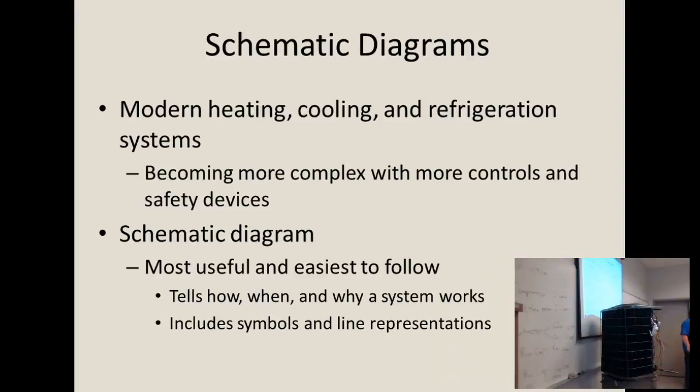What does the T stand for? T stands for load side. L stands for line side. We can't use L for both. They both start with the letter L, so we just chose T's for the load side. The compressor has 3 electrical terminals on it. And we name those 3 R, S, and C, for run, start, and common.